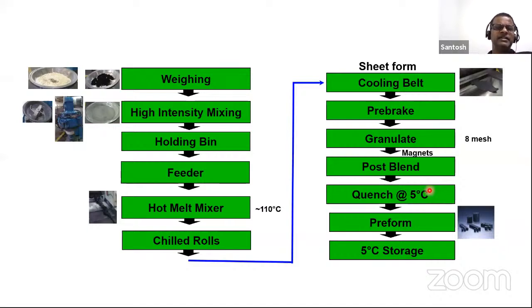A little bit of a hint about the manufacturing of epoxy mold compounds. Basically, it starts with the process of weighing. I have told you about the composition of the mold compound. All these components are weighed into a bin. The black stuff is carbon black. If the mold compound is designed to be black in the final appearance, they put carbon black on top of it. So this is putting everything together in terms of weighing the materials.